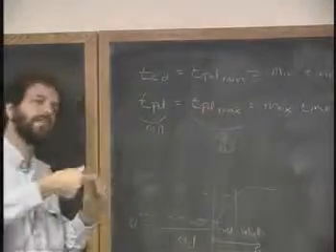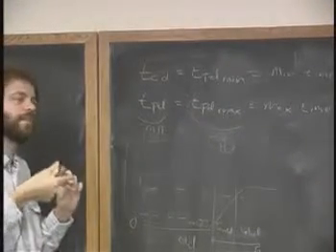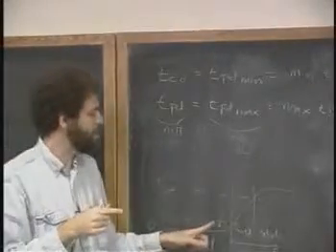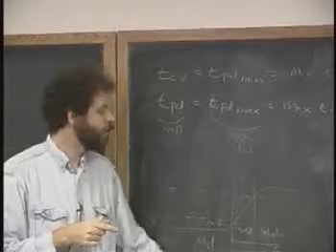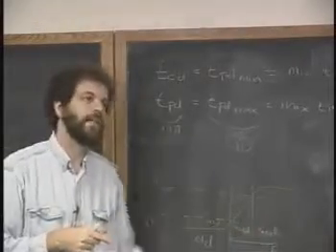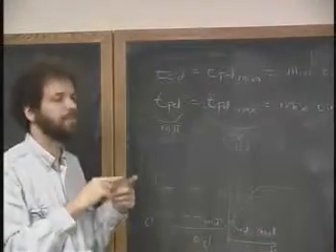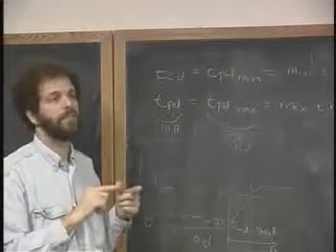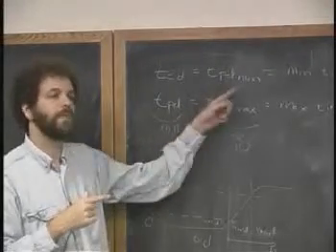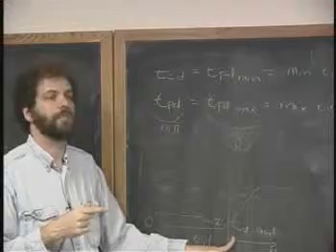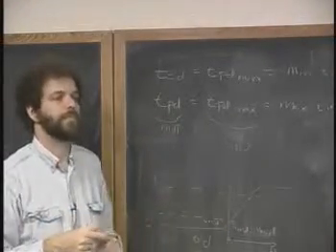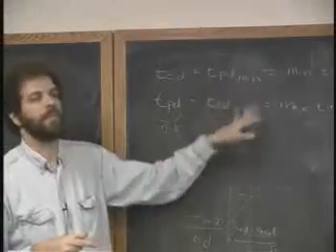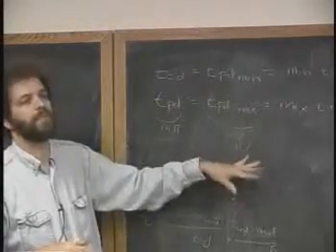So there's sort of two concepts being mixed together here at the same time. One has to do with whether we're measuring time from invalid in to invalid out, or from valid in to valid out, and whether we're doing a measure of min or max. It turns out that we only care about the minimum for the invalid inputs, and we only care about the maximum for the valid inputs. And that's why they're paired up in this way. There aren't 4 possible things to measure, there are only 2.